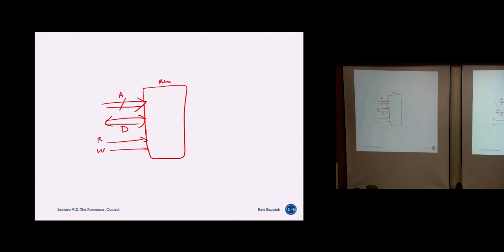So even if I put some value here, I still need to select one of these options. I need to tell the memory chip whether I'm going to read from this address or I'm going to write to this address. So these are all the control lines that you need to connect. And all this goes towards where? Goes towards your microprocessor. In your microprocessor, you have your address bus, your data bus, your control lines, and you need to then come up with a logic, correct? A firmware to interface with this memory hardware device.